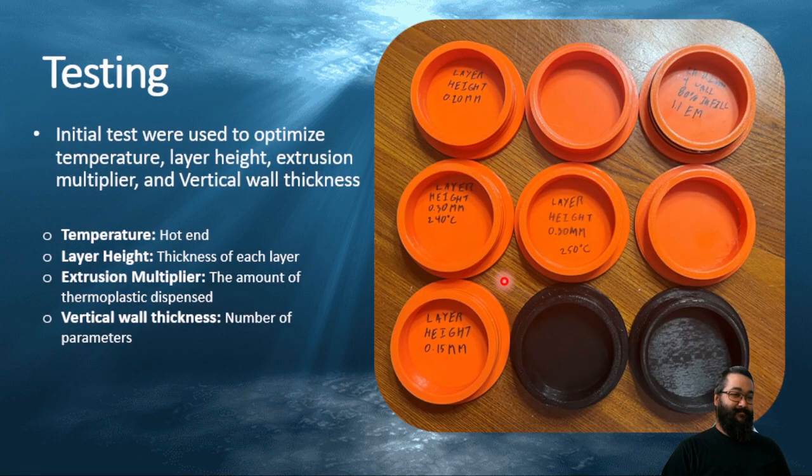Then I had to come up with a form of testing these 3D printed parts. The initial tests were done by trying to optimize temperature, layer height, extrusion multiplier, and the vertical wall thickness. So how did I do this?